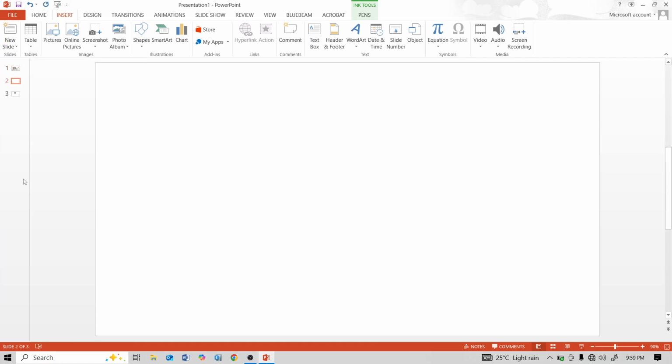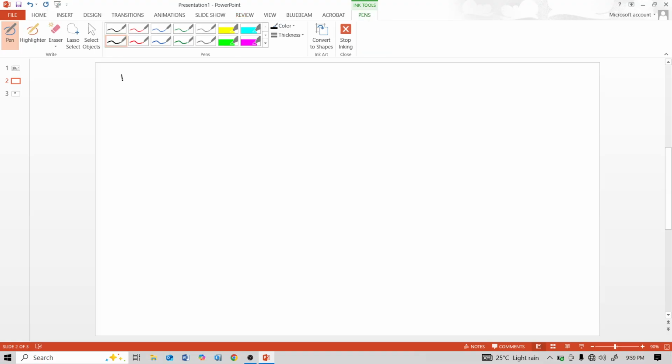Now, by using the flexure formula, M by I is equal to sigma by y. From this formula, sigma is equal to M into y upon I, and this is the stress on face AB.